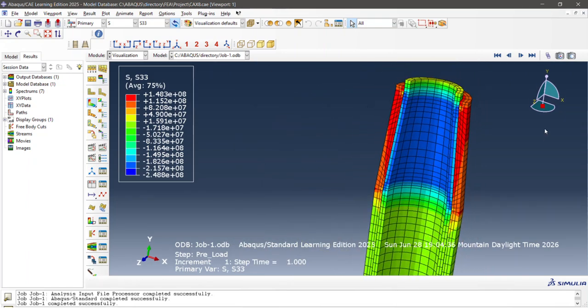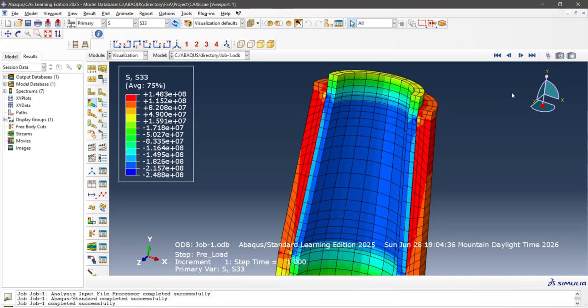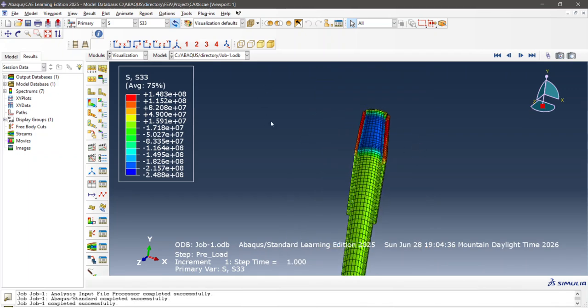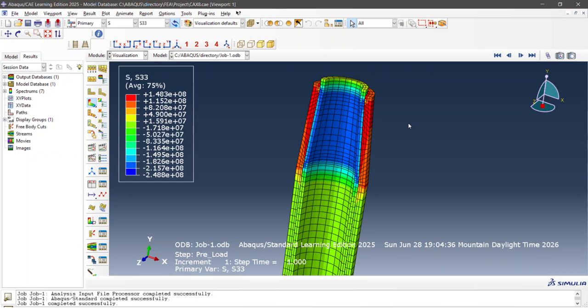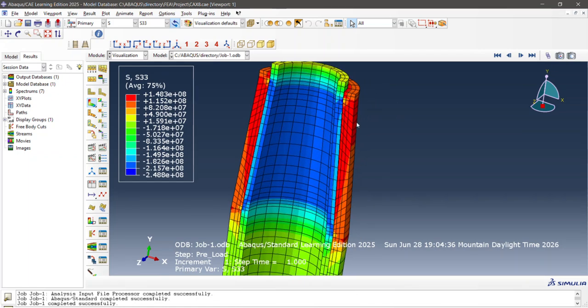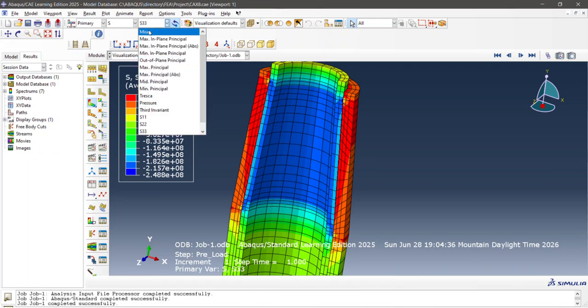Hope this is somewhat helpful and gives you an understanding of an axisymmetric analysis and why they are helpful and useful. They greatly simplify design to keep you from having to have these crazy big 3D assemblies with thousands of nodes, hundreds of thousands of nodes probably for something of this size. And they still give you the information that you're chasing and need to make a decision or to get an understanding of a behavior that you're seeing.